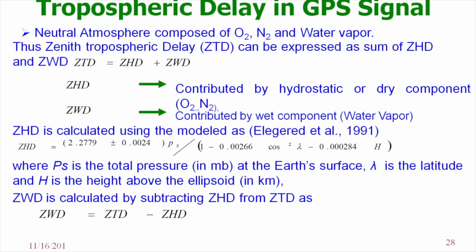Similarly, in the troposphere, there is water vapor. These water vapors are also conductive, they form a dipole. So, this is known as tropospheric delay. So, ionospheric delay and tropospheric delay, these two types of errors are very important, but they are also very good for research purposes. By these errors, we calculate the error and convert it to find the ionospheric electron content and the water vapor content, which I will discuss.